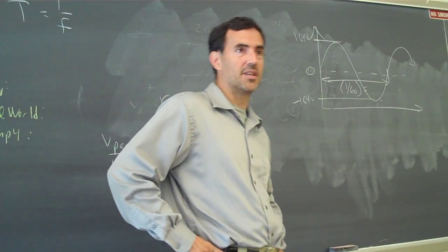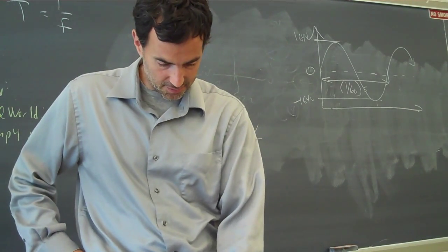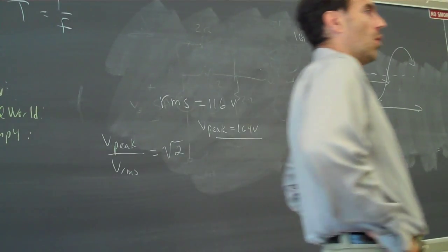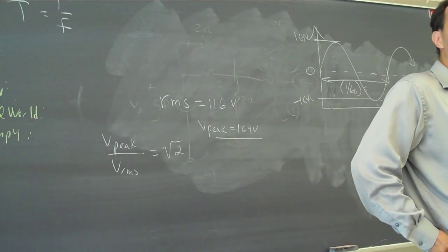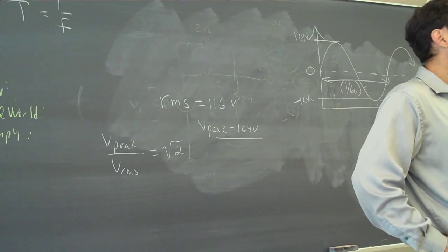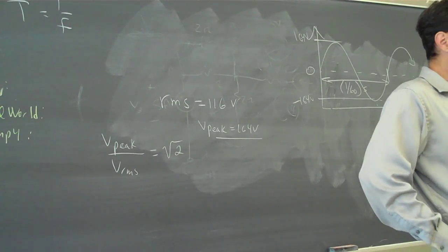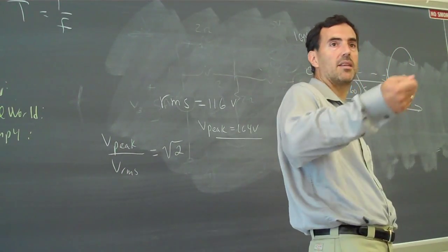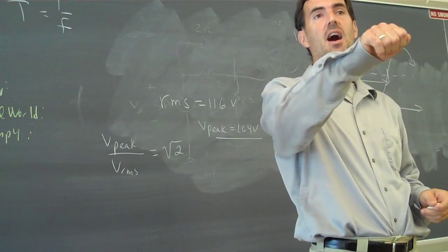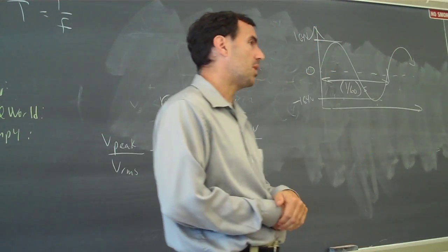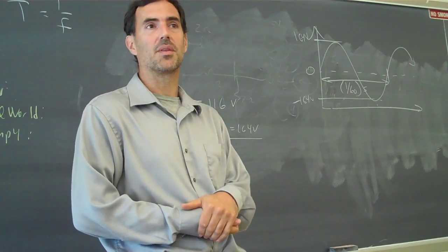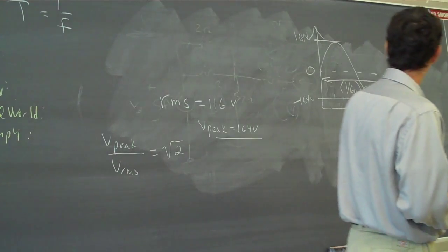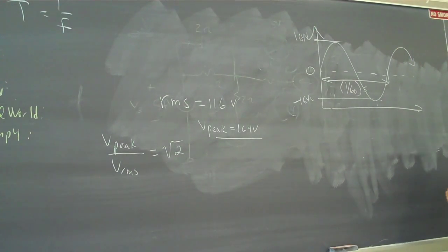You could actually convert that to a decimal. 1/60th is 0.017 seconds. 0.017 seconds is 17 milliseconds. So 0.017, move the decimal place 3 times, I get 17 milliseconds. To see this on the scope, you would have to set the time per division to, I don't know, 3 milliseconds, 5 milliseconds, something like that. So you have 17 for the whole screen. Okay.